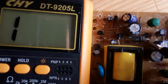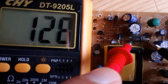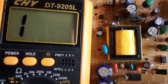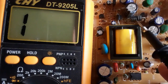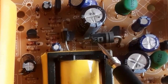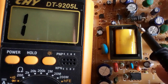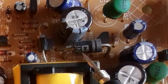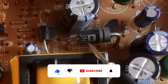But for the Schottky diode, let's check the drop voltage. As you can see, we have a low drop voltage. So the Schottky diodes always give a low drop voltage. Okay? That's why you should never replace a bad Schottky diode with a normal diode or a standard diode. Never. Because if you replace a bad Schottky diode with a standard or a general purpose diode, it will be damaged immediately, because the Schottky diode is a fast switching diode with a low drop voltage.